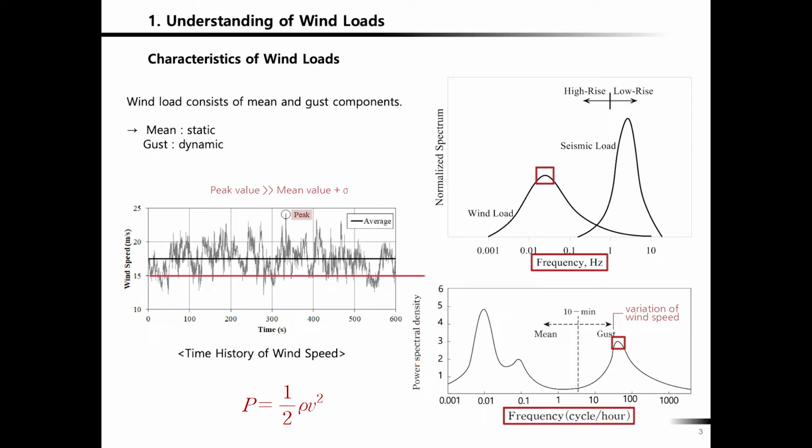You know that the pressure, according to the Bernoulli equation, if velocity becomes 0, then the pressure applied to the obstacle will be 1/2 times the air density times the velocity squared. So we're interested in finding the mean velocity because that's going to be transformed to the wind pressure, and then integration of the wind pressure will be the mean wind force, or maybe the peak wind force.